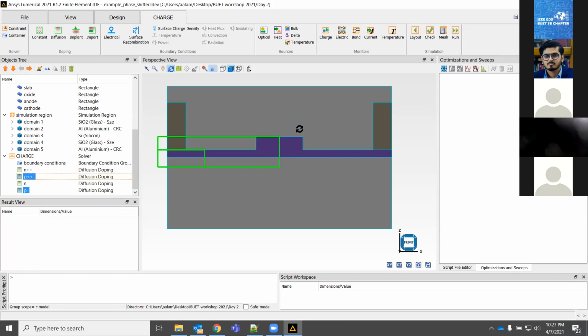And so that's how you can change the optical property of the waveguide by applying a voltage across it. And that's possible because you have formed a PN junction here to start with. So that's one key mechanism that we use to create these phase shifter components, defining a lot of building blocks in active photonics. Whether you're using a ring modulator or a Mach-Zehnder type modulator, the building blocks are these basic phase shifters. And so that's why we created this waveguide and doped it with PN doping, and then we have this contact so that we can apply a voltage.